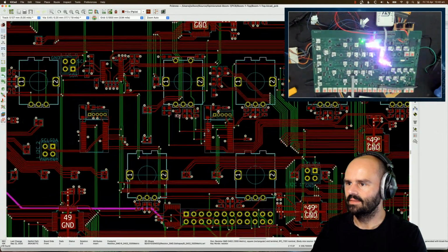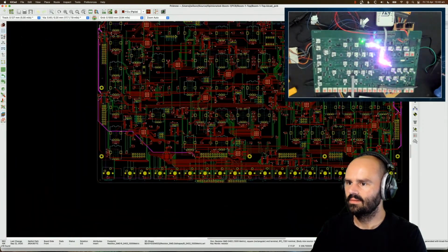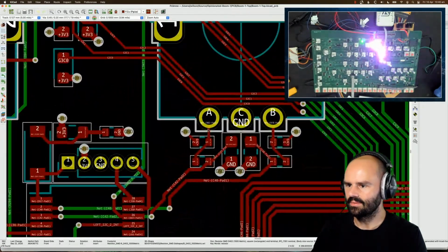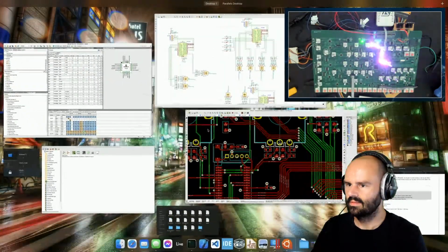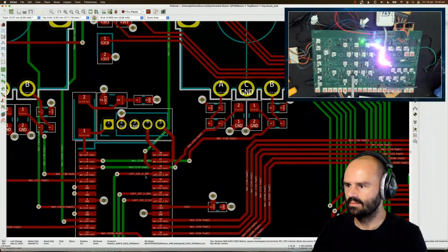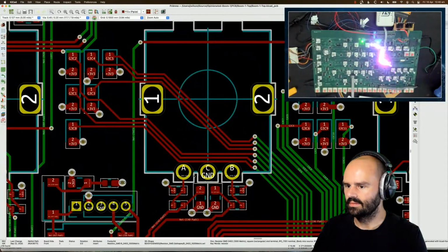So I'm really at a loss to explain why we don't see anything coming through on these pins. Right, because they're pulled high normally, pulled low when there's contact. The pin numbers make sense, right? Pins 2 and 3. There's the second rotary encoder.